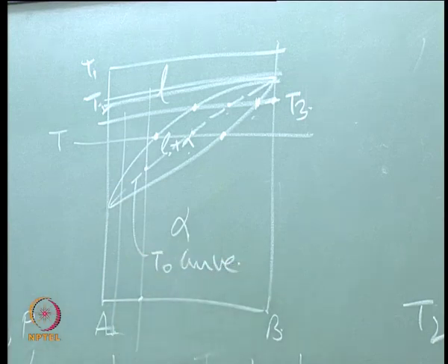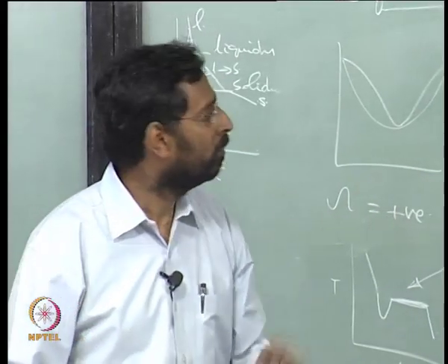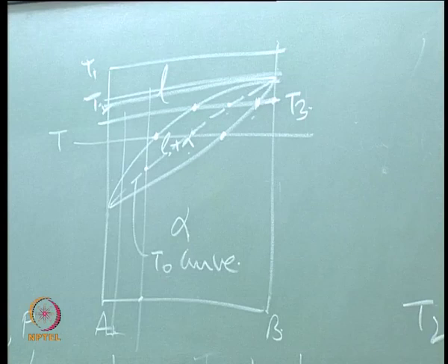And what is the significance of this T naught curve? We will see as we go along. It is a very profound concept, and this is the one which brings you into what are called metastable phase diagrams, and we will see as we go along.